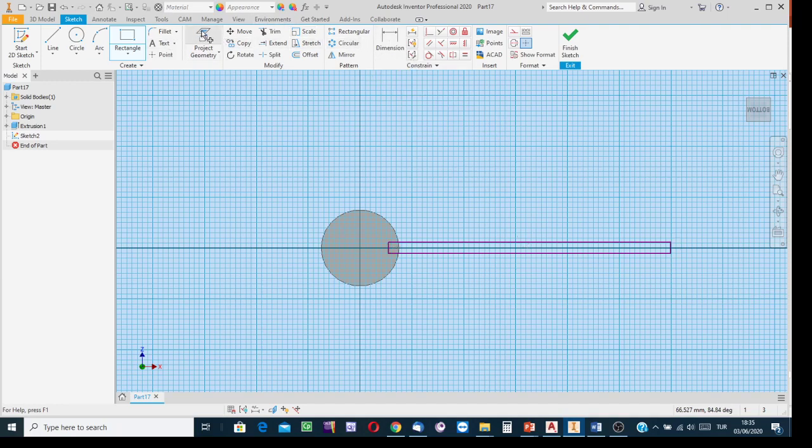So, projection process, project geometry to have the center of this surface, such that it can snap the cursor, so I can indicate it as a point, and with respect to that point can input the size of the sketch items. I apply the project geometry process, and thanks to the projected existence of this circle I can indicate the center. Dimensional constraint, from the center of this projected boundary to the boundary of the profile, say that distance is equal to 2. And the thickness of the base of the thread is totally 4.